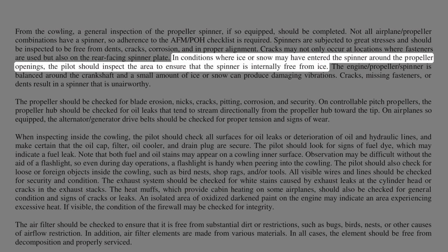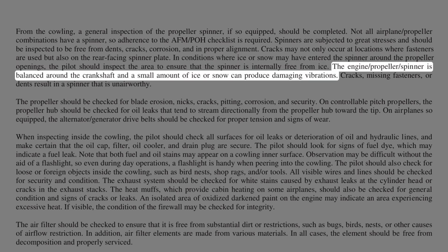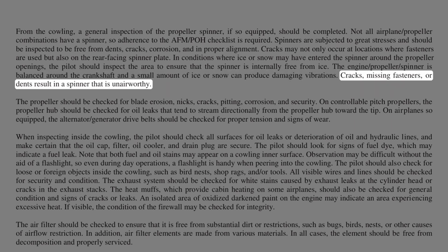In conditions where ice or snow may have entered the spinner around the propeller openings, the pilot should inspect the area to ensure that the spinner is internally free from ice. The engine, propeller, spinner is balanced around the crankshaft, and a small amount of ice or snow can produce damaging vibrations. Cracks, missing fasteners, or dents result in a spinner that is unairworthy.